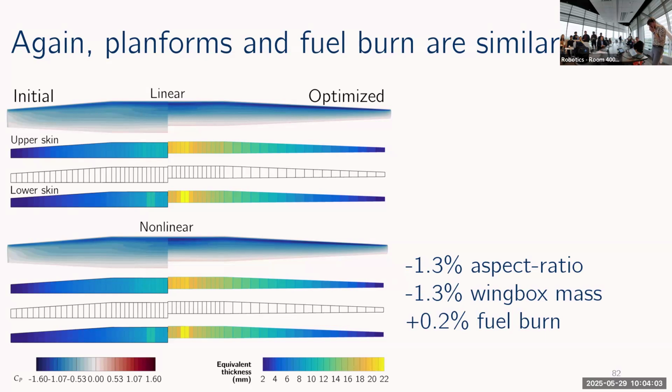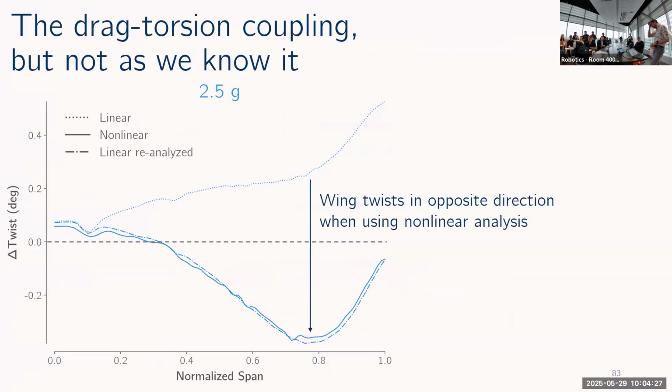And when I plot the lift distributions in the maneuver condition, there's a small difference, but as I say, it doesn't seem to affect the eventual structural mass of the wing. I'm trying to figure out what it is that the optimizer did to compensate for that. Actually, it didn't really seem to do that much. The jig twists of these two designs are a little bit different, but it seems like the performance was relatively insensitive to those differences in jig twist, which were of a similar order of magnitude, like half a degree.